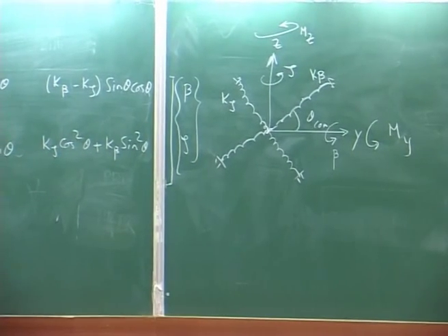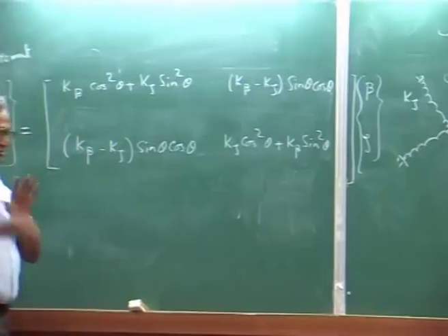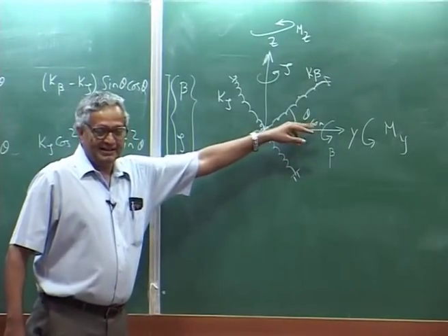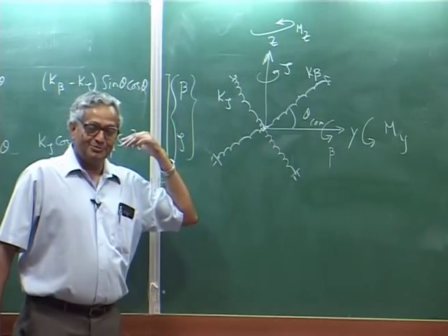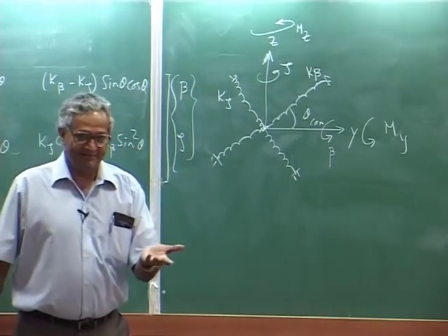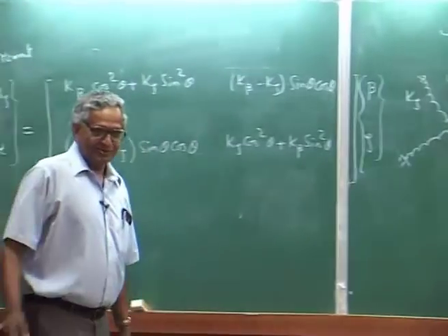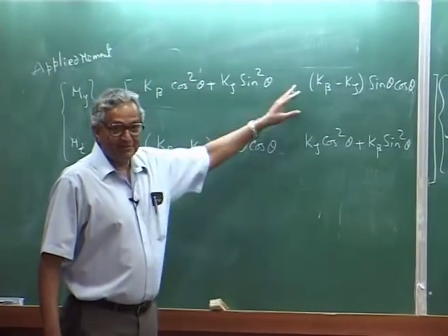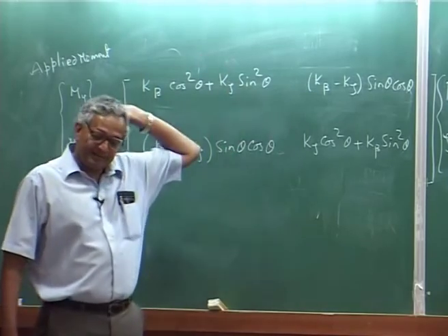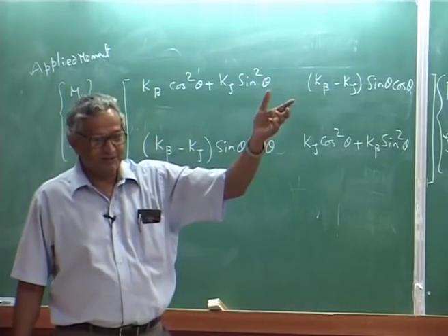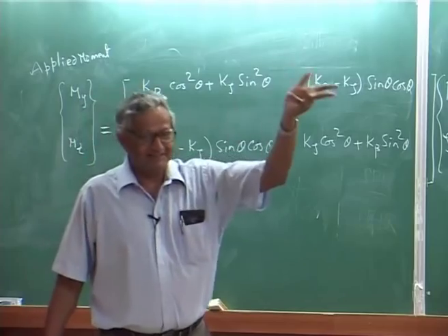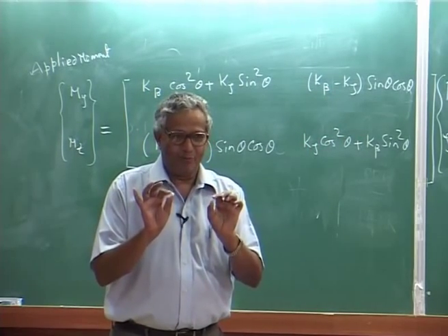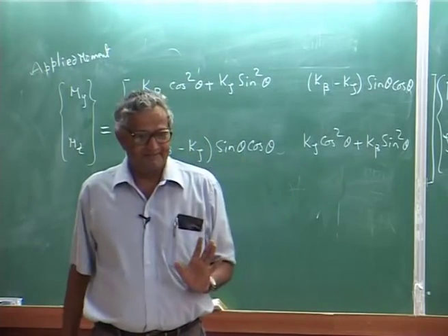Now, in the NASA report what I used was minus beta, okay, and then I get not an applied moment, I used the restoring moment. So, I put one more minus sign. So, you will find that there will be some sign difference between this and there, and in some other research paper you will find there will be some other sign, but you have to be careful what sign he has used for everything, okay.